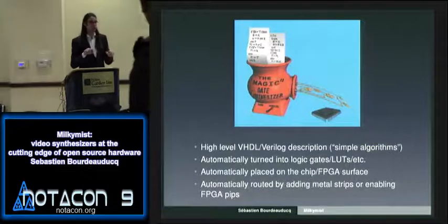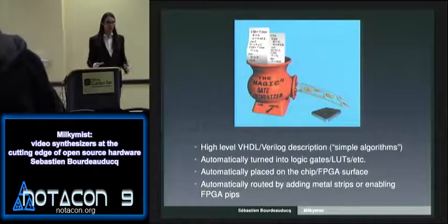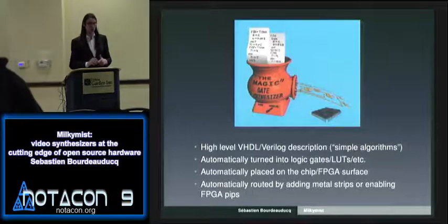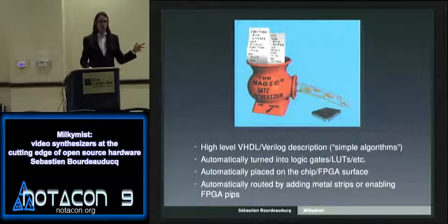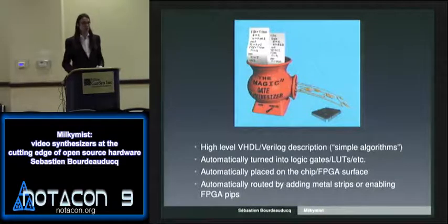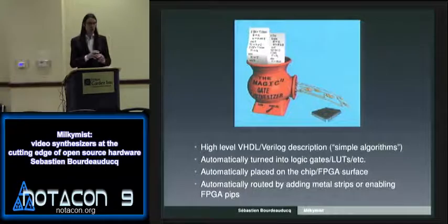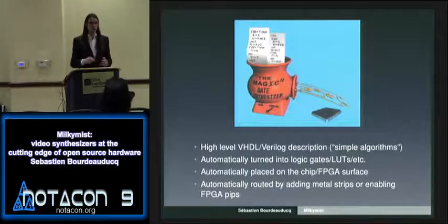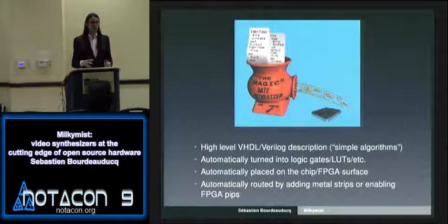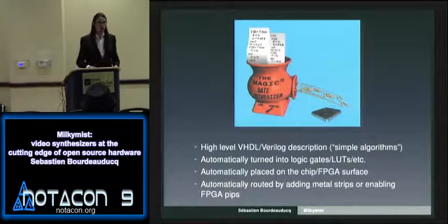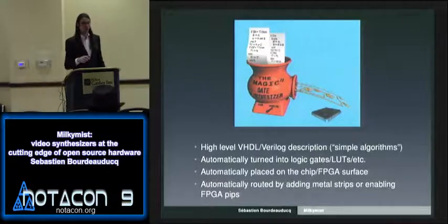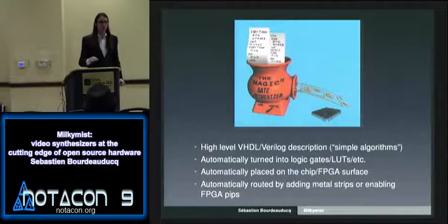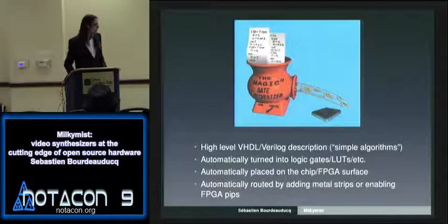Actually, it can be TTL chips. It is theoretically possible to develop a synthesizer which automatically partitions and selects TTL chips for you. But typically, when you have a logic design written in VHDL or Verilog, TTL chips are way too small for implementing such designs. So instead of TTL chips, you use what is on the chip of the TTL chip. That is what is called the standard cell in ASIC designs. It's basically a pre-made semiconductor layout for, let's say, a D flip-flop or an AND gate or anything, and the synthesizer can pick up the correct gates from this pre-made library and use them to implement the behavior that you have written using VHDL or Verilog. And so that's for making actual chips.